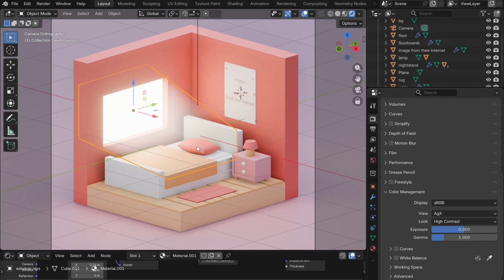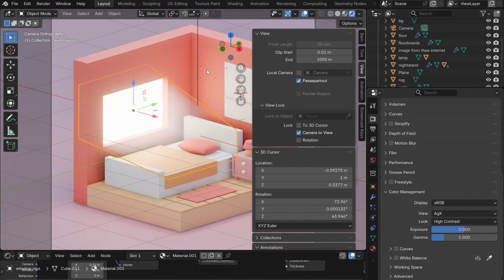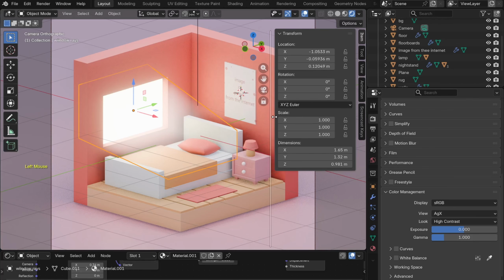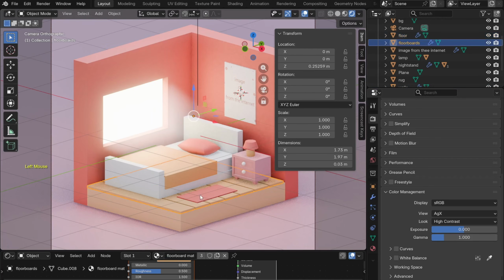You'll find both the animated and non-animated .blend file inside that. Before we start animating, we need to make sure the objects have the scale applied. To know if an object has the scale applied or not, expand the sidebar by dragging the little arrow, or press N. Here in the Item tab, if you see the scale values are set to 1, that means the object has applied scale. If it's other than 1, then you need to apply scale. So let's check all the objects which will be animated if their scale is right or not. And I will apply the scale if it's not applied yet.